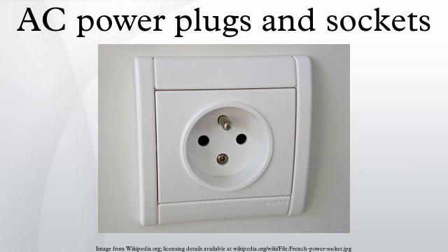Italy. Italian earthed plugs and sockets are defined by the standard Serie 23-50 which superseded Serie 23-16. This includes two models rated at 10A and 16A that differ in contact diameter and spacing. Both are symmetrical, allowing the line and neutral contacts to be inserted in either direction. This plug is also commonly used in Chile and Uruguay.